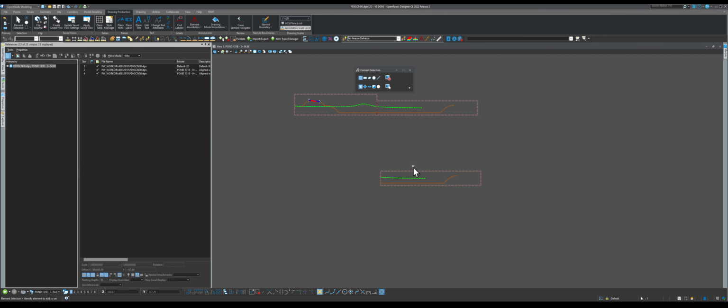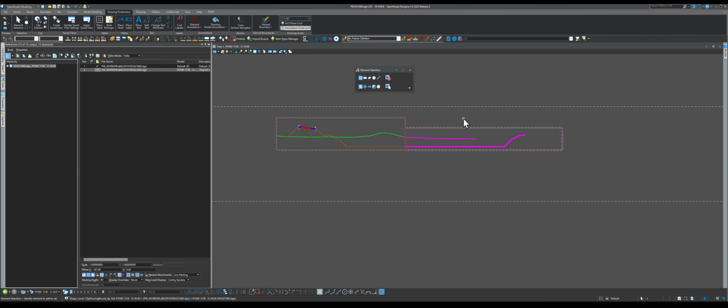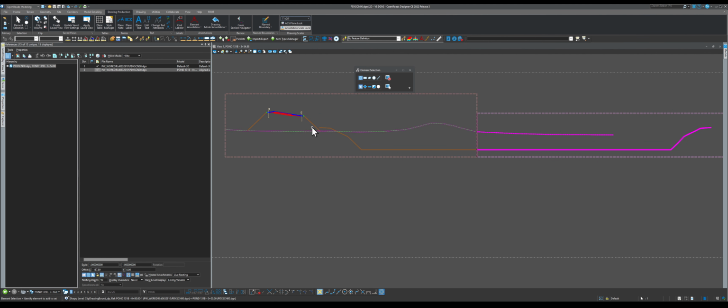So in that case, and let me tell you why I wanted to copy. I wanted to copy just so you can keep them as reference, meaning reference window from the 3D model. So in case an update happens, you can update. But in this case, we don't need that. We can just go straight up to dropping them. Meaning, what I'm about to do right now will disconnect them from the 3D views and just have them here as solid lines, as just dummy lines. So only do this if you know you are done, you are good, there are no more updates, the roadway already fixed their stuff, and you are good to go. Or the roadway already knows they're going to fix their stuff, so you can manually move this.